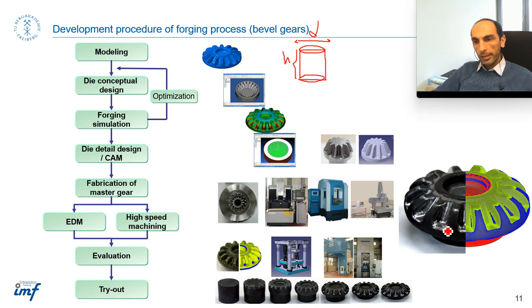And here you can see the comparison between the model, the simulation, the predicted. I don't know what is predicted here. Okay, but you can compare, and even the direction of the workpiece, putting the workpiece into the die is important. Sometimes during the deformation you rotate the billet, for example, after the first stage or second stage, then you rotate it 180 degrees upside down, and then another step. This also could be designed just to optimize the metal flow line, and or I can say to optimize the mechanical properties, and sometimes to minimize the forging load.